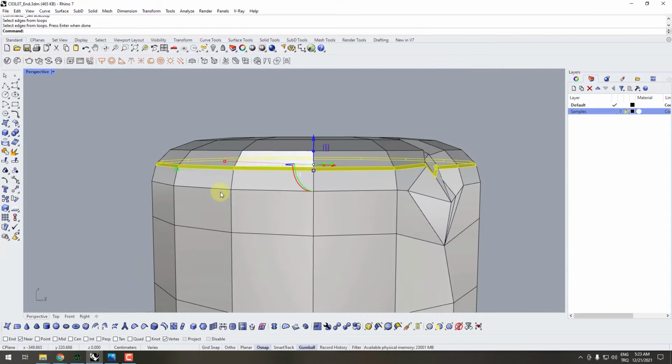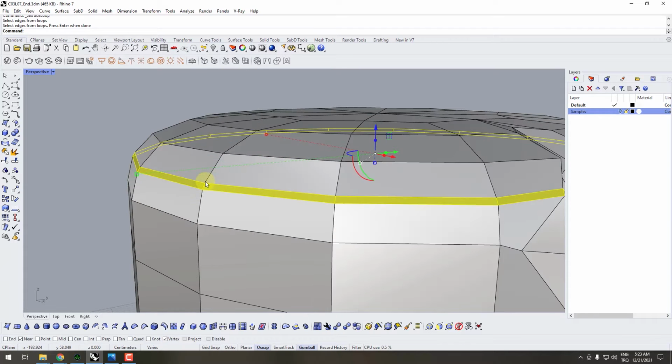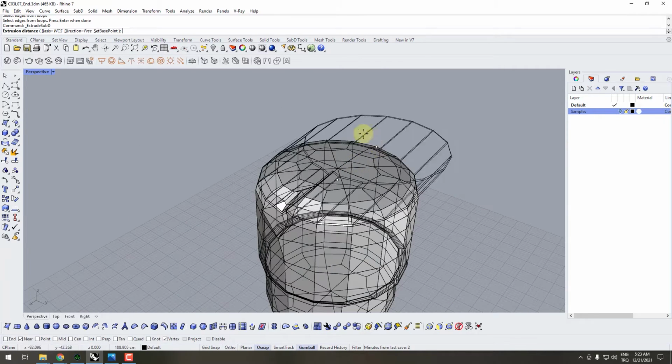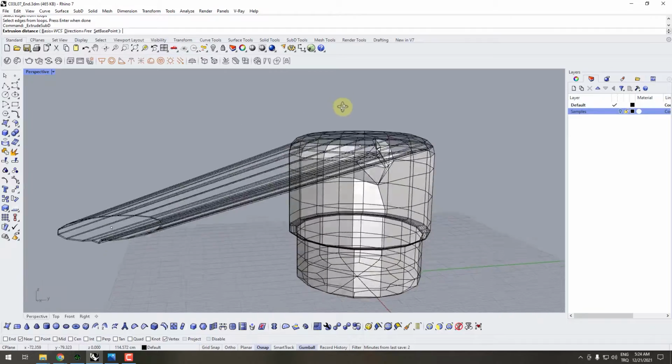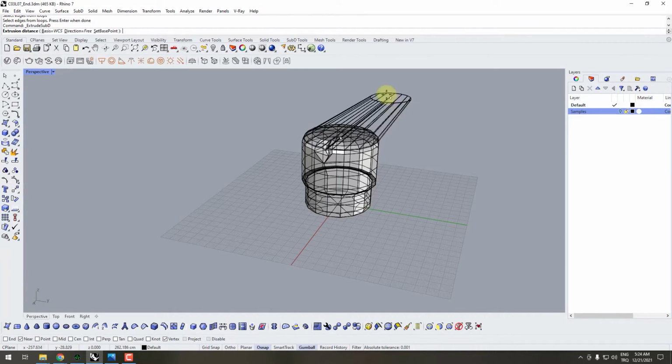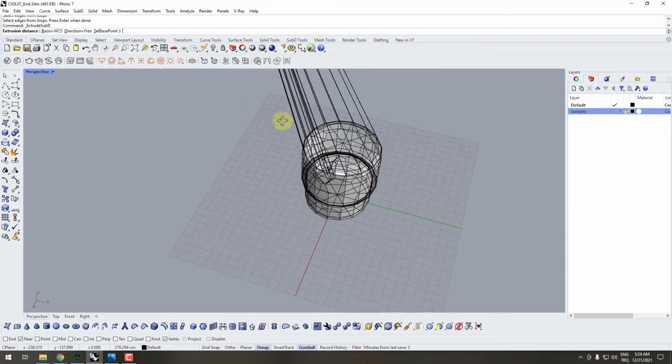What we need is not to fiddle with the size of these surfaces. We need new surfaces extruding from these surfaces. So we will be using the extrude SubD command, which you can find in the middle section of our SubD toolbar. After selecting the surfaces, I'm left clicking the extrude SubD command. It starts to create surfaces starting from the originally selected surfaces. By default, it creates surfaces to the place you click with your mouse.